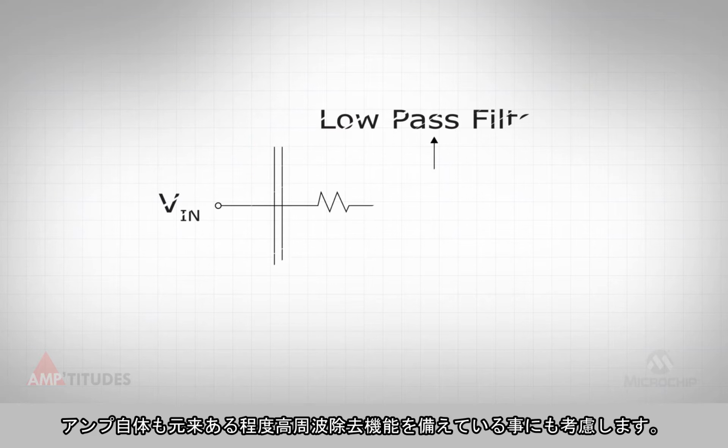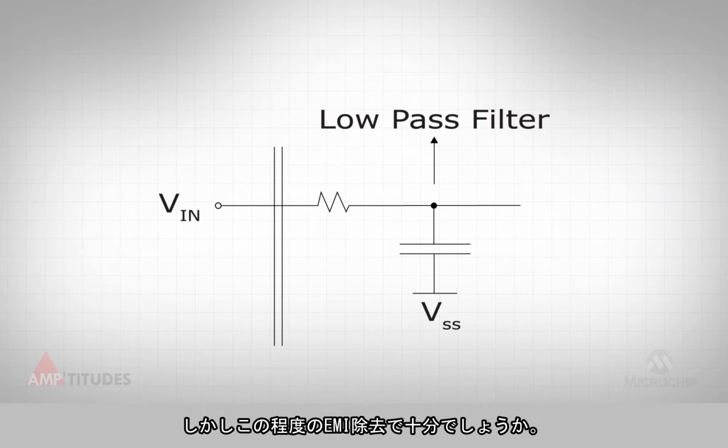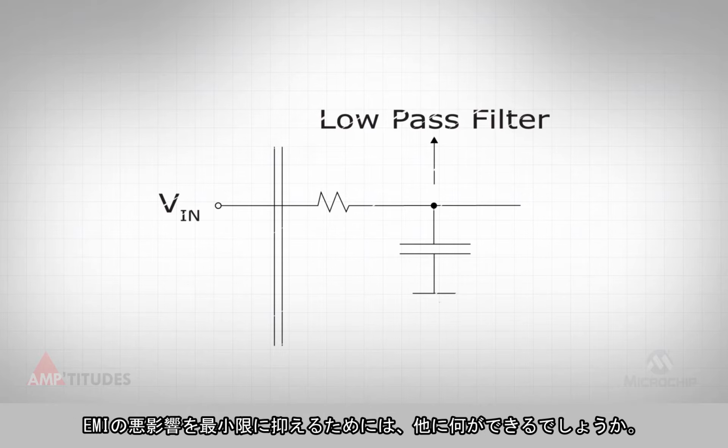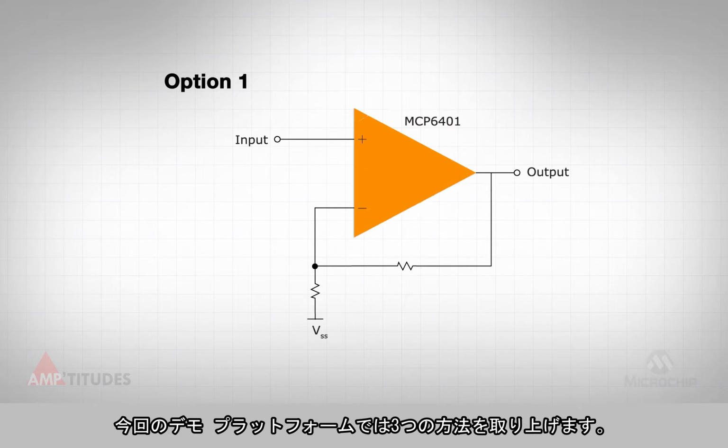It should also be noted that all amplifiers inherently have some level of high-frequency rejection. The input impedance and parasitic capacitance on the inputs form a low-pass filter function. But is this level of EMI rejection enough? What else can be done to minimize the adverse effects of EMI? This demonstration platform highlights three potential options.